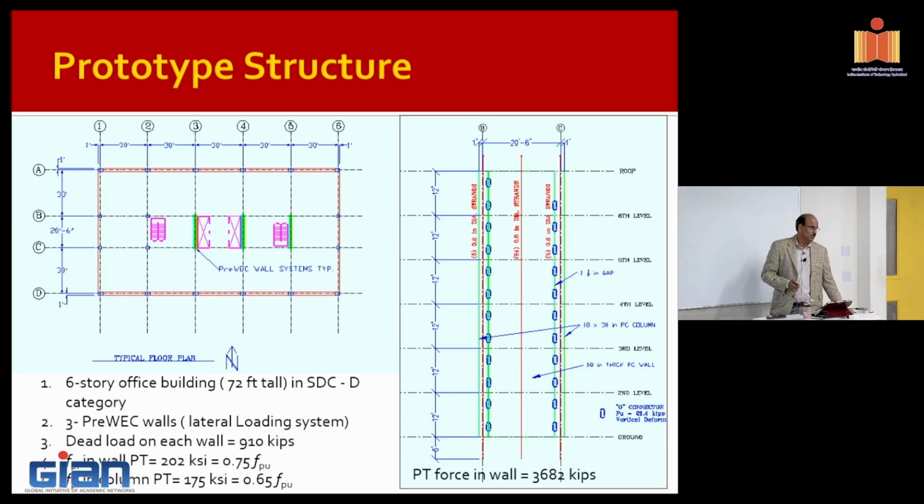In other words, the compatibility in terms of load transfer: whatever load gets generated on the floors has to be transferred to these gravity beams and down all the way to this frame. So the connections, I think we talked about it on and off in terms of how important that is. Then your purpose should be to take that load and transfer it all the way to these frames. And they provide the resistance.